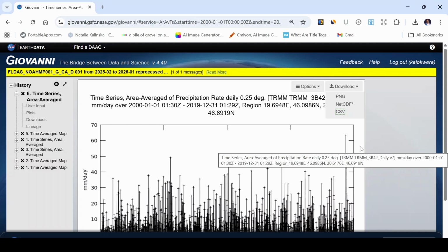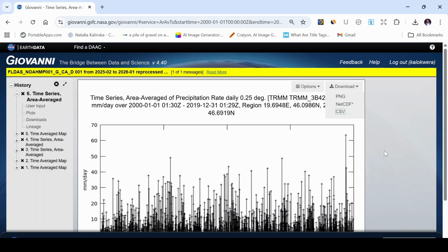The second thing I do is cross-check with CHIRPS. I also use CHIRPS rainfall data as an independent satellite product. Now, when two independent data sets agree reasonably, confidence increases. So make sure you take note of that. It's even better if you have the station gauge data, the TRMM data, and then the CHIRPS data. From here, you can do some correlation analysis or check for the bias, and then see how to correct that bias before using it for your design.